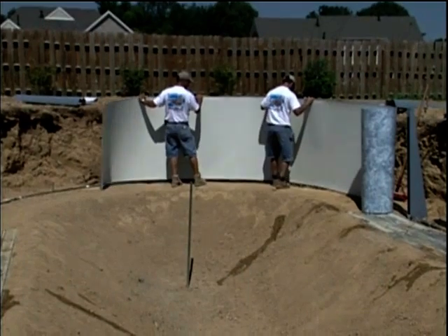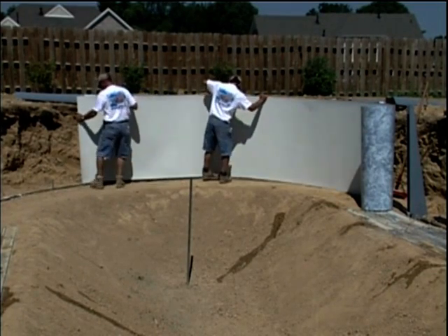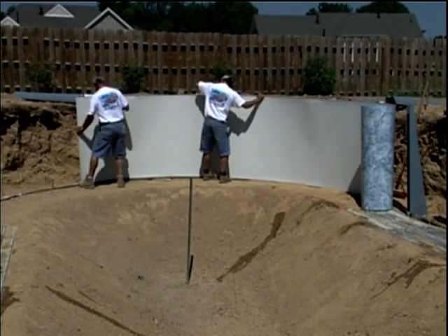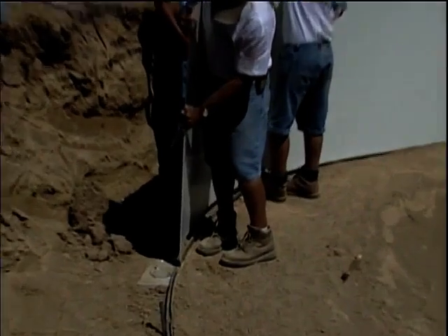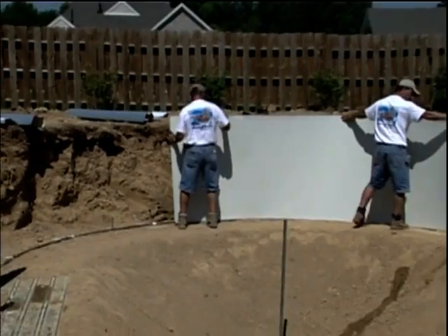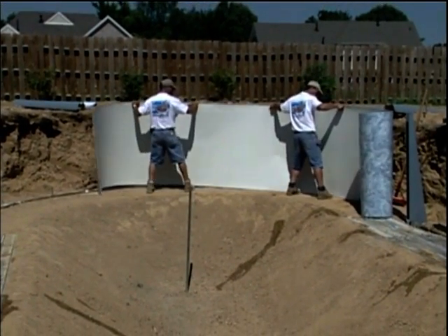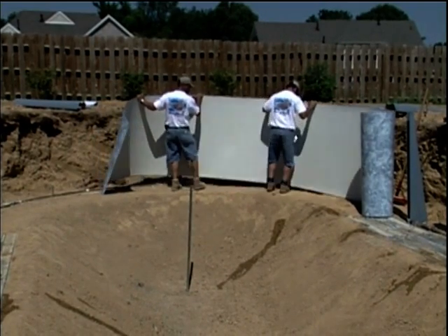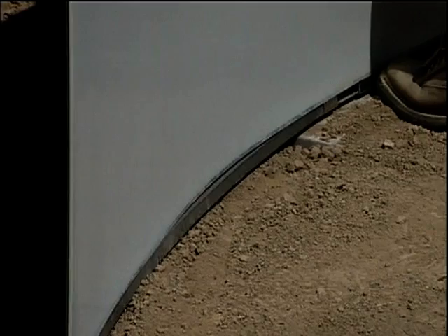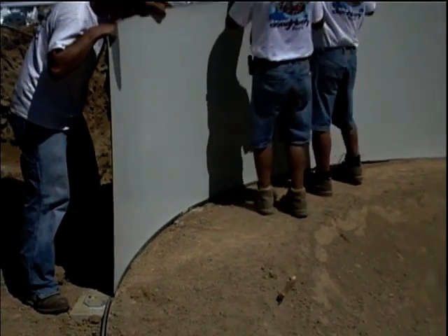Also remember, installing the wall is a team effort, and it works best if only 6 to 10 feet are unrolled at a time. When starting the wall, align the starting edge of the wall on the center of the vertical end cap where the starting point has been determined. As you start to uncoil the wall, remember to keep your hands and feet from between the wall and the bottom rail. As the wall is uncoiled, secure the wall from one vertical end cap to another by inserting the bottom edge of the wall into the groove of the bottom rail.